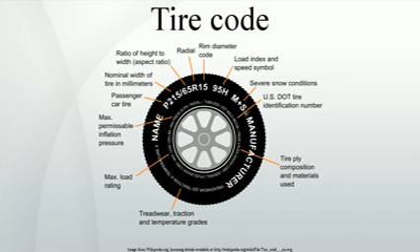Examples. The tires on a BMW Mini Cooper might be labeled P195/55R16 85H. P: these tires are for a passenger vehicle. However, P denotes P-metric size; load and speed rating changes for P tire and non-P tires. 195: the nominal width of the tire is approximately 195 mm at the widest point. 55 indicates that the height of the sidewall of the tire is 55% of the width, 107 mm.